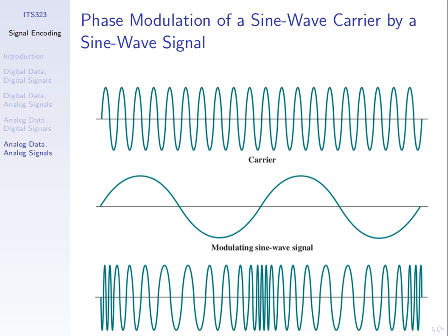That's the bandwidth. And the transmitters must be designed to transmit at no larger bandwidth. For example, they can use filters to filter out any unwanted frequencies in the transmitter. So if you transmit at a wider bandwidth, you are breaking the conditions of your license, and you can lose your license, for example. So there are commercial or financial penalties in that case.